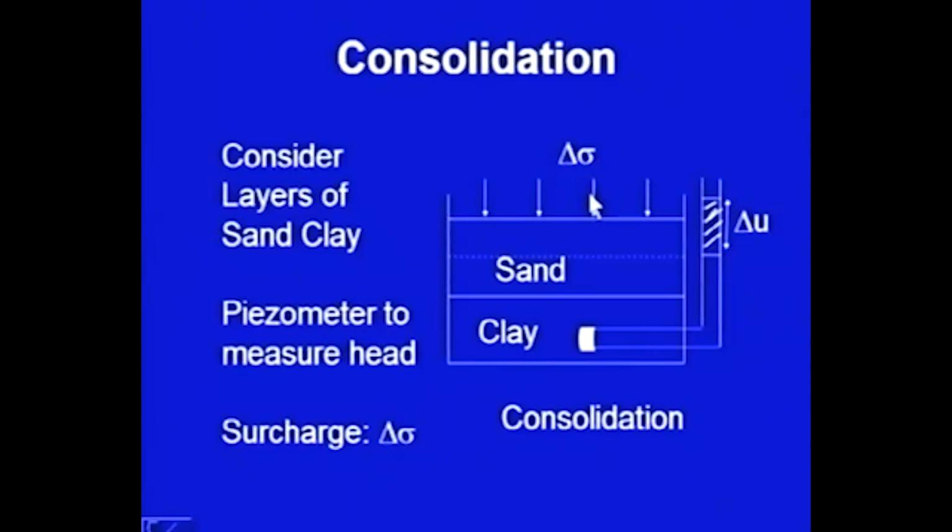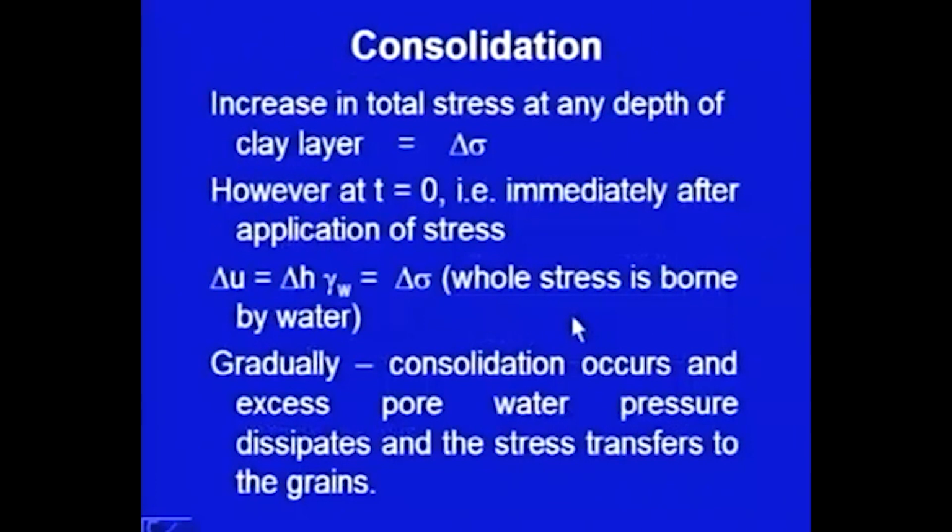Surcharge means some weight, maybe a building is constructed at this place. When you put this surcharge, the weight will be transferred to the sand, and to this particular clay layer. In the clay layer, though it is completely saturated, initially the water will be bearing that load, and because of that the pressure in the water will be increasing.